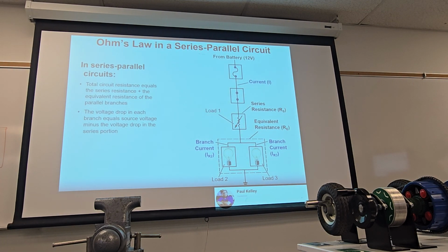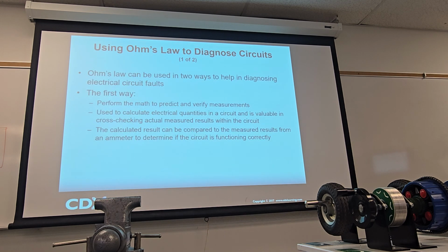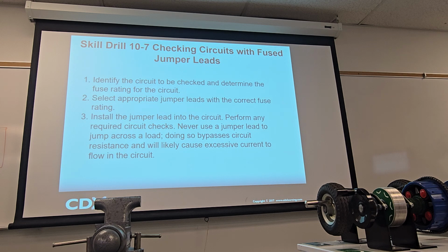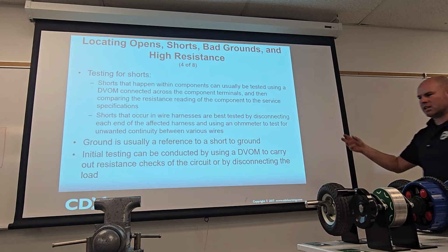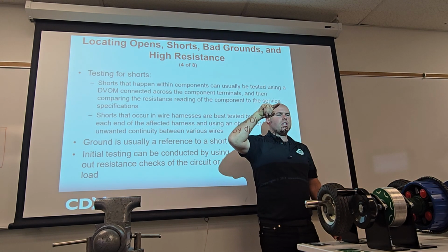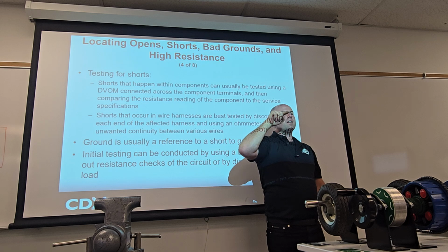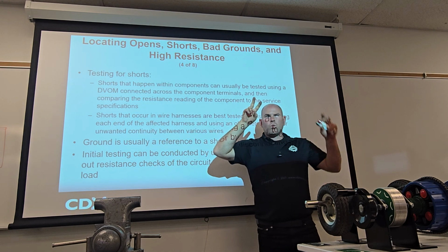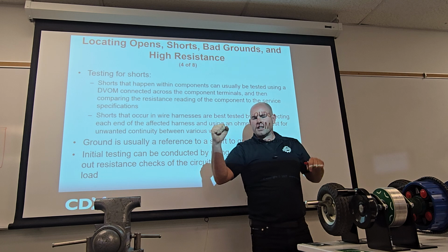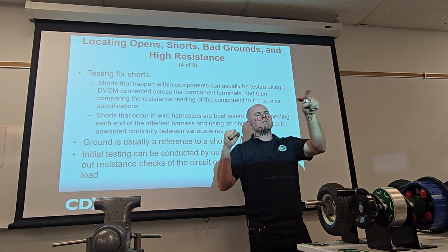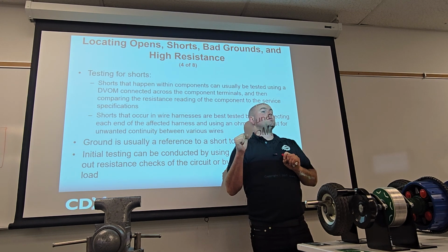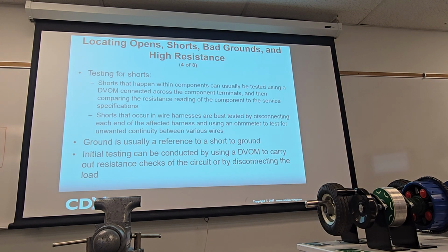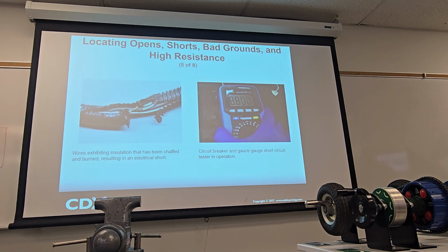The test light, hook that screw. Yes, exactly. It depends on how you had the test light hooked up. If you were trying to see if that screw was shorted to ground, you'd actually hook the lead of your test light up to the positive battery terminal. Then everything you touch with the test light that's grounded would light it. Makes sense? Because what's normally the ground of your test light would go to positive. Then everything that lead touches that is lit would be ground. That screw's grounded. Oh, I see. That wire is shorted to ground, etc. Cool. So that mostly makes sense.